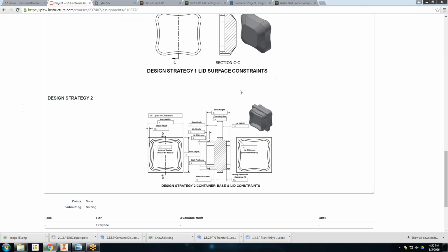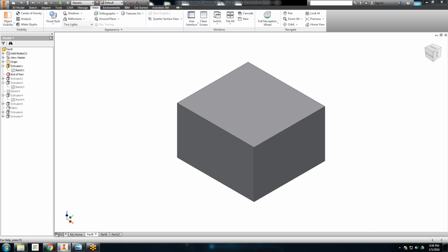And what we did today is I printed this document out, and they all started filling it in with me. So stock width was 3 inches, stock depth was 3 inches, stock height was 2 inches, and so on. Once I've got all that, I tell them that in real life, most people designing things don't truly think about it: if I design this as perfectly a 3x3 and my stock is roughly a 3x3, I can't get the part out of there.